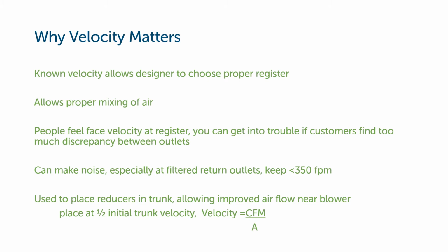Well, why does velocity matter? Velocity allows us to choose the right register. It allows the right mixing of air in the room. I think it's important to note that when you feel the air blowing out of a register, you're feeling the velocity. You're not really feeling the CFM or the BTUs. You're feeling the speed of the air. And it's good design practice to keep the velocity the same at all the registers.